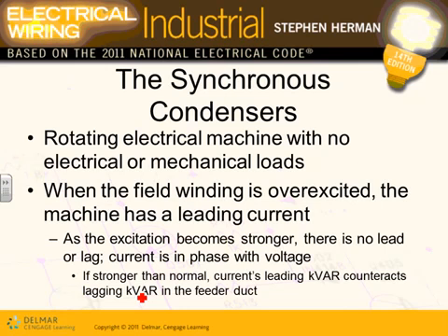Another method of correcting the power factor, guys, instead of adding capacitors, is adding synchronous motors. Synchronous motors, I don't know if you touched on them too much. We talked about them a little bit. They run at synchronous speed. If you overexcite them, you're going to see they talk about excitation of motors. They put DC in the coils, the armature, actually the stator. They put DC on them to overexcite them. Long story short, if you overexcite them, they start actually generating kVAR for you. So they act like a capacitor.